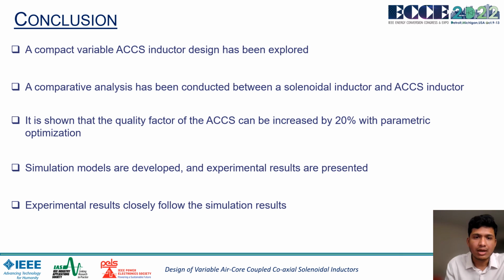In conclusion, a compact variable ECCS inductor design has been explored. A comparative analysis has been conducted between a solenoid and ECCS inductor. It has been shown that the quality factor of the ECCS can be increased by 20% with parametric optimization. Simulation models have been developed. Experimental results are presented. The experimental results closely follow the simulation results.